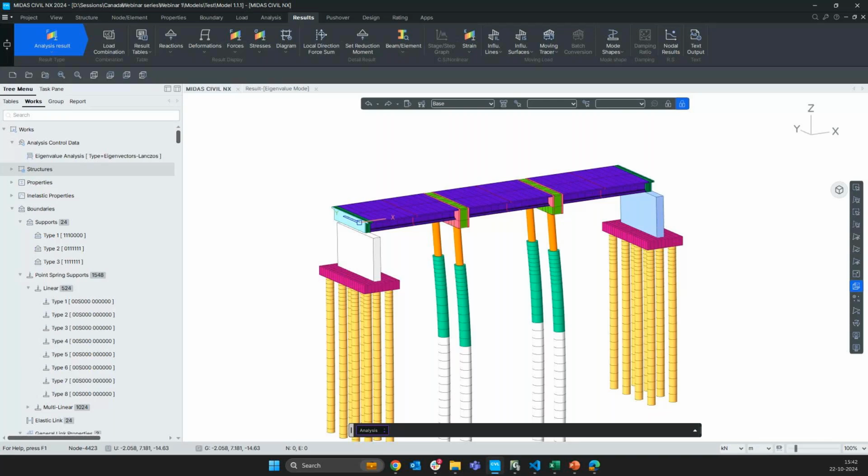So for this, one method is to develop an Excel sheet wherein we can compute the deformation coming into the structure under the first iteration, and reassign the spring stiffnesses for that particular point.